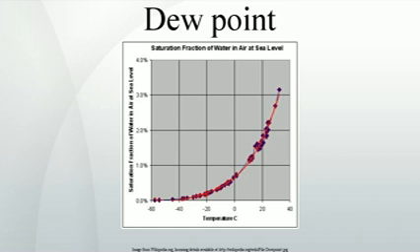Relationship to human comfort. When the air temperature is high, the body's thermoregulation uses evaporation of perspiration to cool down, with the cooling effect directly related to how fast the perspiration evaporates. The rate at which perspiration can evaporate depends on how much moisture is in the air and how much moisture the air can hold. If the air is already saturated with moisture, perspiration will not evaporate. The body's cooling system will produce perspiration in an effort to keep the body at its normal temperature even when the rate it is producing sweat exceeds the evaporation rate.